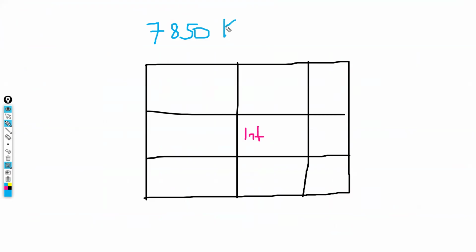But this is kilogram per cubic meter. So you need to convert it into Newton and then have it in kilonewton per cubic meter. We need this measurement in kilonewton per cubic meter. How do you convert from mass to weight? This is mass multiplied by the acceleration, so mg.